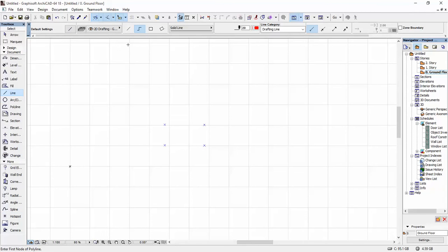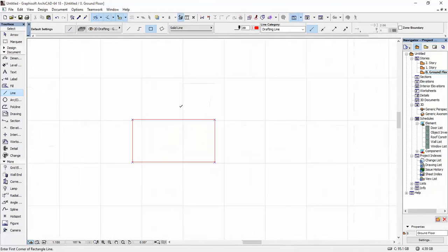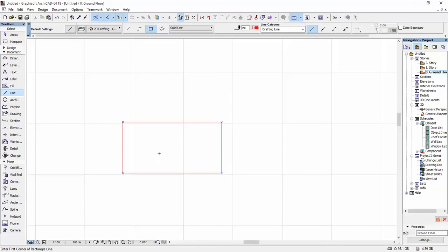To help me, at first I'm going to put these lines. I'm going to draw the rectangle. I'm using my line tool, and I selected the geometry method rectangular, and I drew a rectangle. What's going to be inside this rectangle is going to be the pattern of the fill. So now you're going to draw here the pattern that you want to have. You have to keep in mind that this is going to be multiplied to the right, to the left, upward and downward. So you have to have a certain continuity to the lines that you draw.